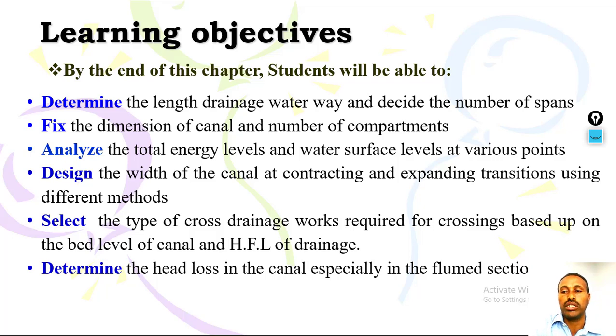So having this in mind, what is a cross drainage structure? It is a structure carrying the discharge from a natural river or stream across a canal intersecting the stream. So you may just have obstruction for a canal due to river, natural lakes, etc., or different water bodies. So how do you cross this water body or river just for the canal, for water conveyance structure, or sometimes for irrigation purpose? So we have just different systems or types.